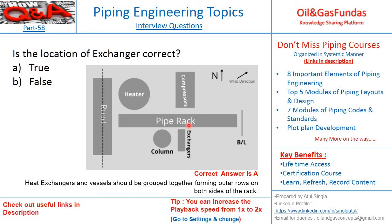Another aspect which we need to take care of is that any heat exchanger shall be associated with a column or maybe some other item. So in this case we are having a column and exchanger, so exchanger should be placed near to this column so that inlet outlet piping, if any, can be minimized. Number one, it is perpendicular to this heat exchanger, the bundle removal area is okay, and it is close to the associated vessel. Moreover, it is near to the pipe rack also, because a few lines may enter through the pipe rack and connect to the column. So this location is correct with respect to the current layout. So the answer is A.